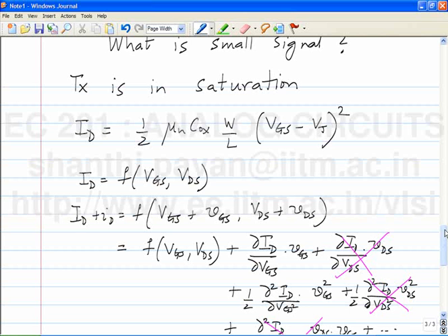We saw this even in the single dimensional case, where the definition of small signal is not any absolute number, but it depends on the nature of the nonlinearity. Okay? And in the single dimensional case, if the IV curve does not depend on the two-terminal device, and the I versus V was like this, so this was V and this was I, what is small signal for this device? Any signal is small signal for a device like this. Do you follow? We've done this before.